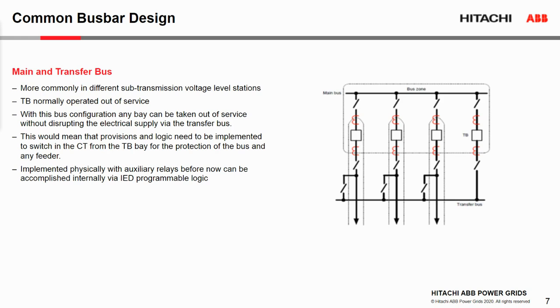Any of these two CTs need to be able to protect any of these three circuits. This type of switching logic was conventionally realized with auxiliary relays, but now it can be easily accomplished internally by IED programmable logic.